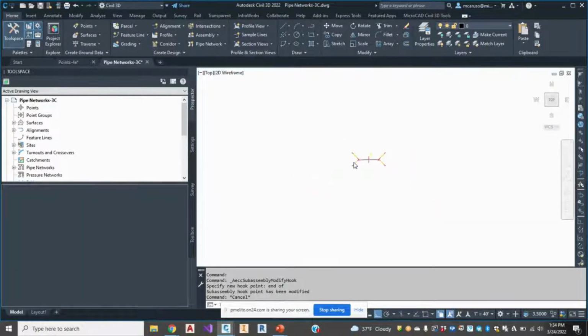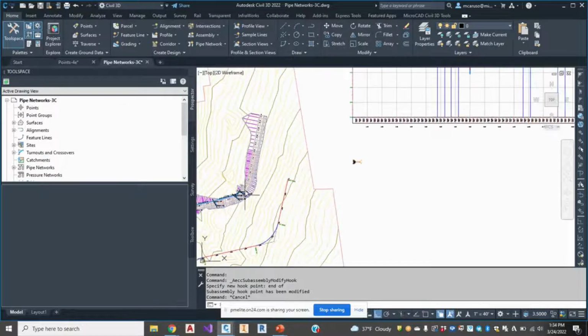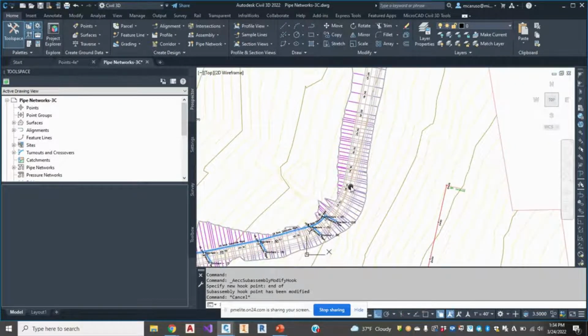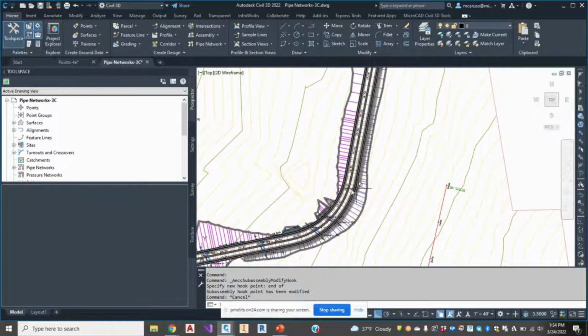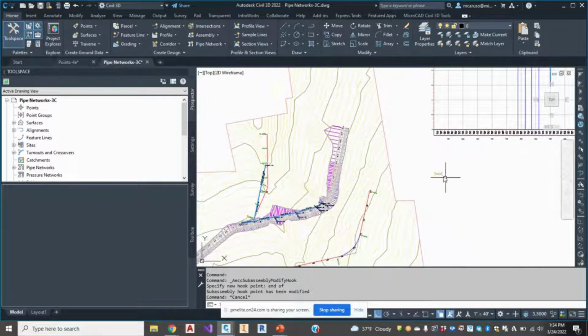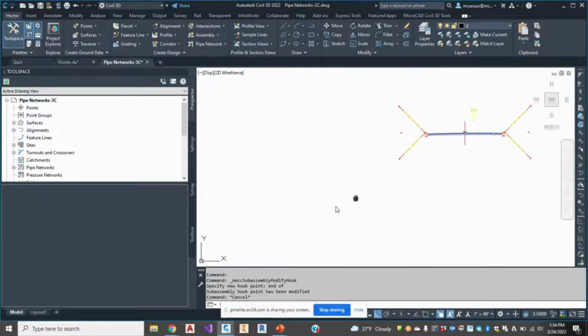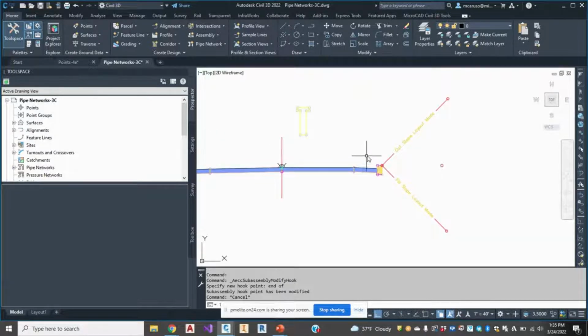So to the left here, zoom out a little bit, I have a corridor object, which is our 3D road model in Civil 3D. And the way that the 3D road is made is from stringing together these assemblies. So here's a cross-section of our road. And then the cross-section is made from smaller parts like lanes and shoulders and curbs. And we have a library of these subassemblies that comes with Civil 3D. And sometimes they don't have the exact cross-section shape that you want. For instance, maybe there's a custom wall to be built over here along the sidewalk.